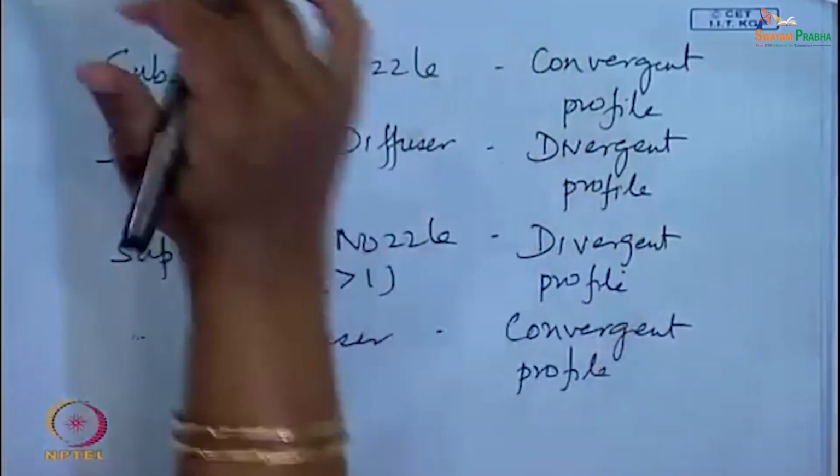Okay. So, this is something very important that you should note: the behavior of compressible flows is not consistent over the entire range of Mach number. One type of flow characteristic is exhibited for Mach number less than 1, or under subsonic conditions, and just the reverse type of phenomena is observed for supersonic conditions. That explains why Mach number equal to 1 is so important. For Mach number equal to 1, it is usually termed the choked flow condition, or the condition of choking.